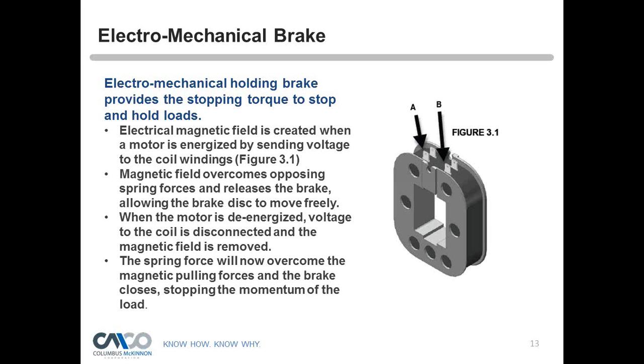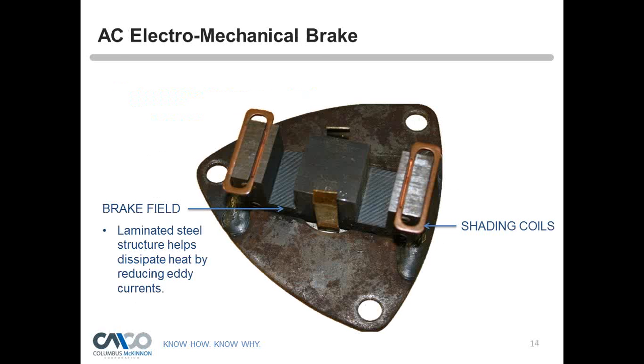So, two very important things, right? The coil, which releases the friction discs, and the springs are very important. So then you can kind of see why that gap is important as well. And so that's basically how the brake works. So let's take a closer look at the brake field.